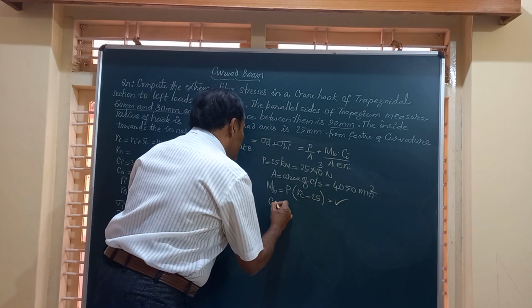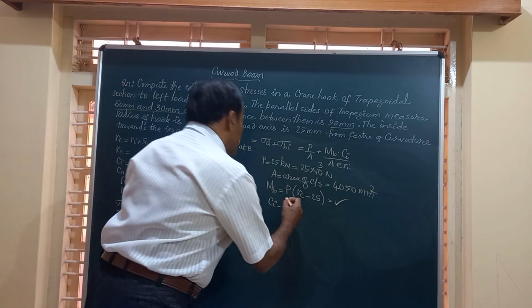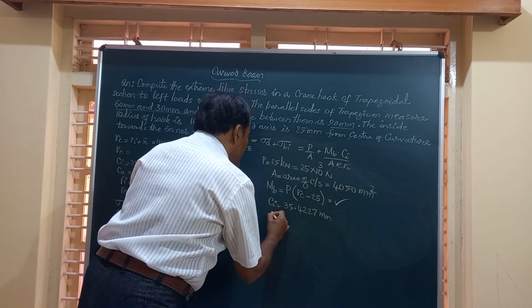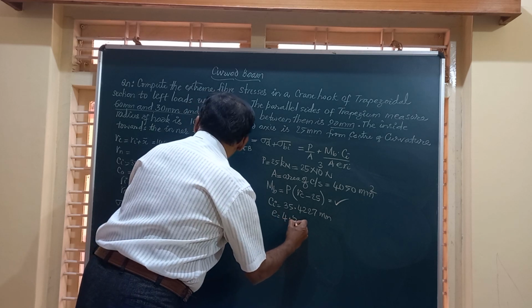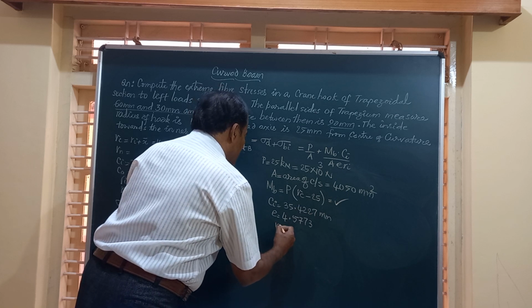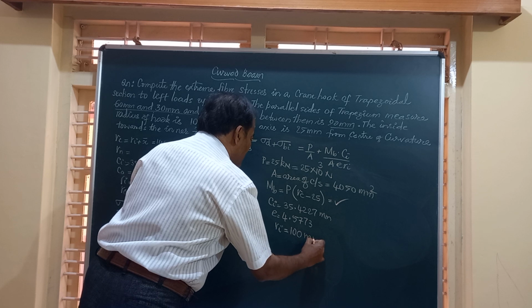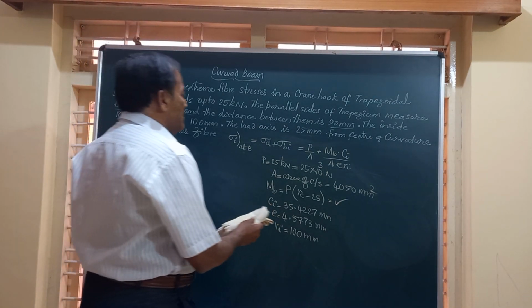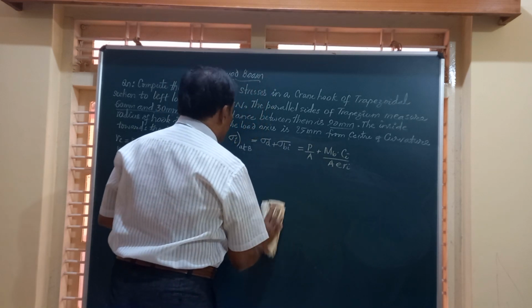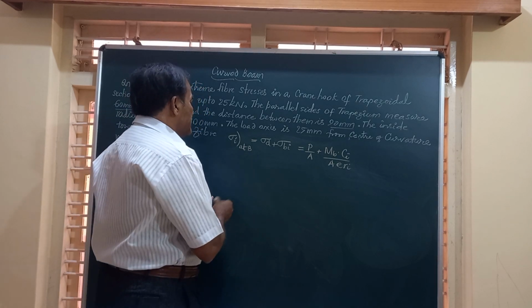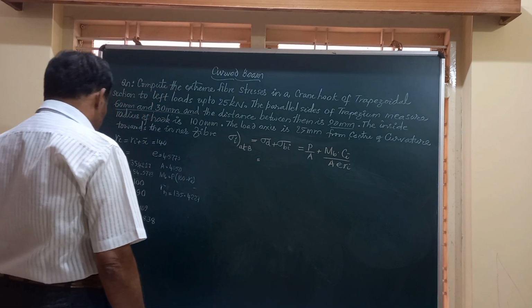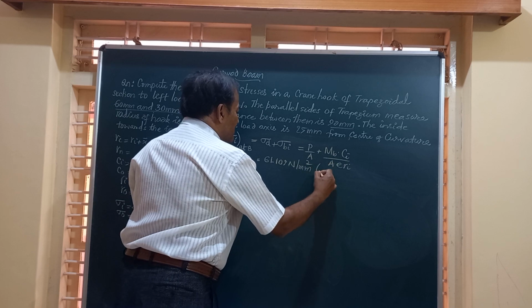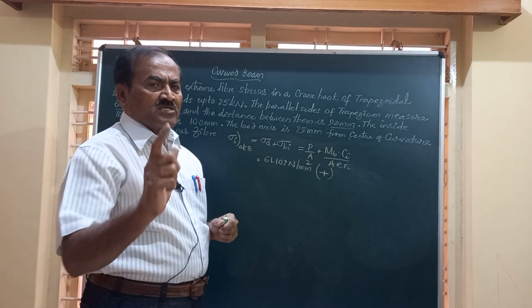Then friends, the value of CI, we have got the value as 35.4227 mm. MB, CI, area we know, e value you know is 4.5773 and Ri value is 100. So friends, we have got all the values required to compute sigma I. If you make all these substitutions in the formula, you get this value of the fiber stress at the inner fiber, that is at B, as sigma I 61.109 Newton per mm square. So this is a tensile stress always for any crane hook irrespective of the cross section.